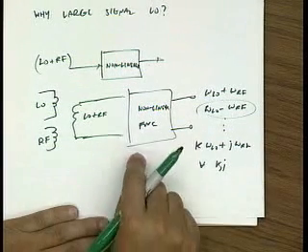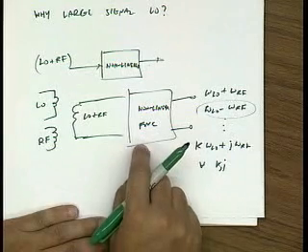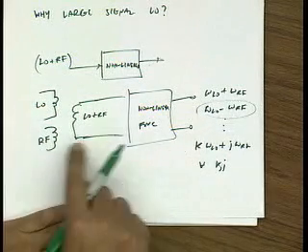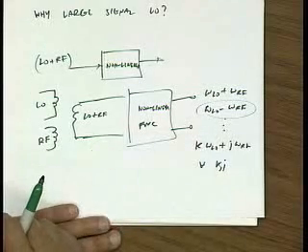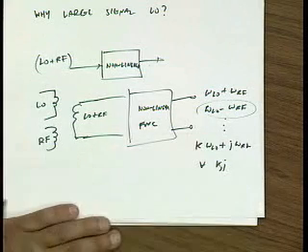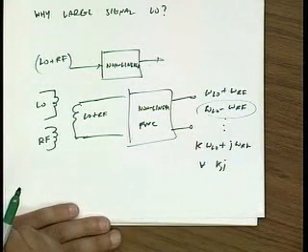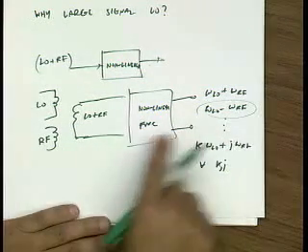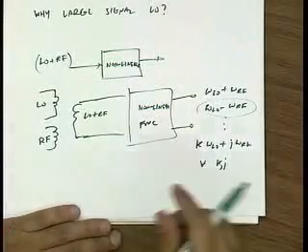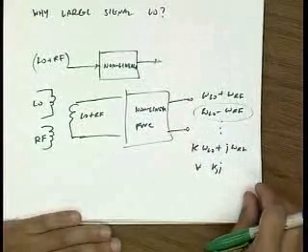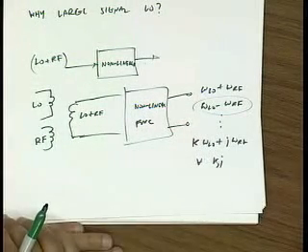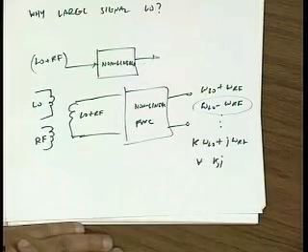So what is the advantage of making the LO signal large? Well, the advantage is that the conversion gain of this mixer is quite low. In fact, I'll encourage you to analyze this, maybe in a homework, or maybe on a midterm or final, and compare the conversion gain of this circuit to the one we just analyzed. But it's a very good question. It's a very valid point. Essentially, any nonlinear circuit, if you put in your LO and RF, will generate conversion products.